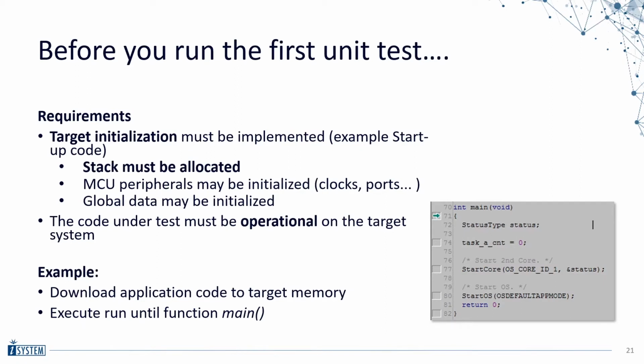One requirement of testIDEA is that stack memory must be initialized. You could also initialize MCU peripherals, clocks, I/O ports, external memories. The code under test must be operational on the target system in order to be tested. The most basic initialization would be to download the code under test to the internal memory and run until main, thereby initializing the stack.